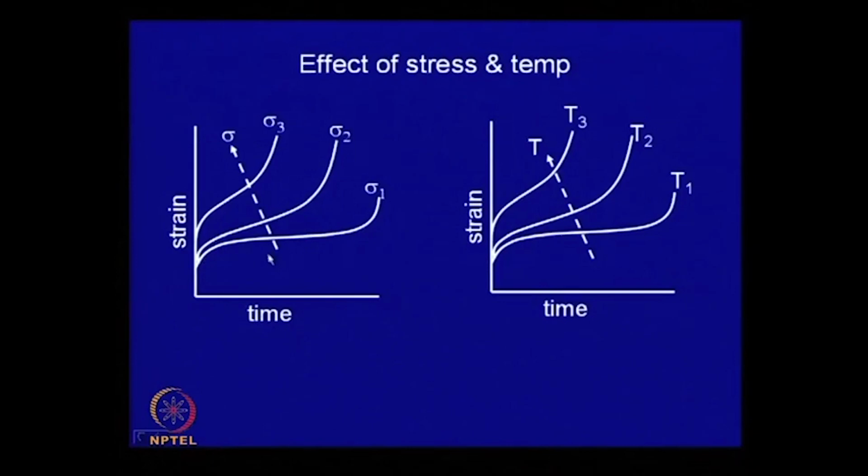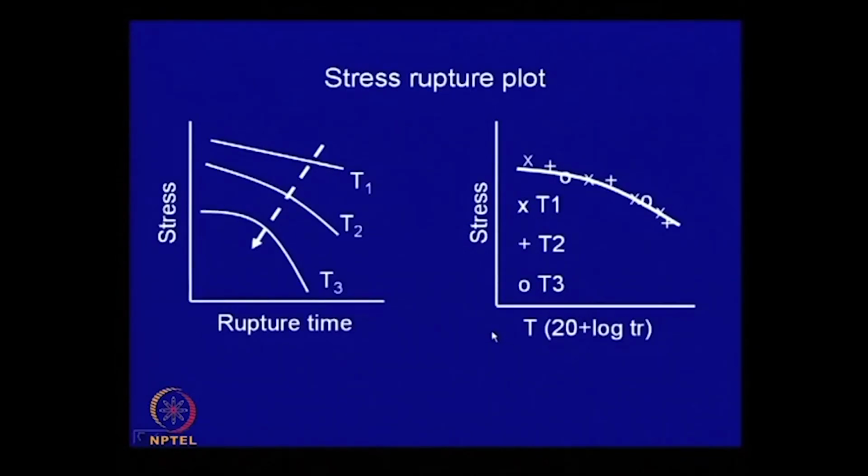This shows the effect of stress. You increase the stress, it fails at a shorter time. This is the time to fracture. You increase the temperature, then also with increasing temperature the rupture time goes down. So, that means it is a strong function of stress and temperature.